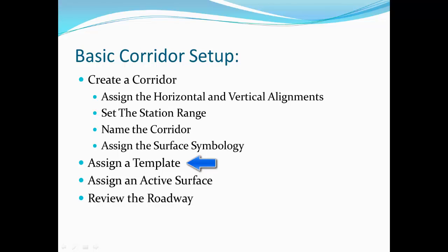The software does allow you to drop templates at wide intervals of, say, 25 feet or 50 feet and then densify the model in the horizontal and vertical curves. But I do not recommend going this route for projects with intersections and gores, since we will need to tighten up the template drop spacing in those locations. The densify option will tend to crash the model if you try and densify when you have added very tight template drops that you will need in the intersection and gore modeling areas.